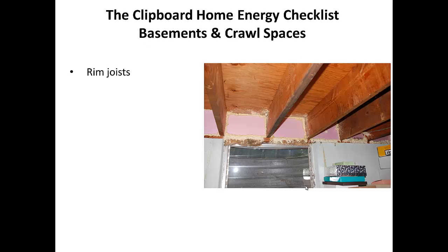So now let's go take a look at basements and crawl spaces. And here we're looking at a foundation wall and the first floor that's above it. And you can see what they've done here again with that Great Stuff foam. It looks like what they've done here is taken some blue board styrofoam and cut it fairly close to the opening dimensions, stuck it in there, and they don't have to do it a very perfect job because this foam is going to fill in any gaps that you would have. So this is a great way to reduce both air infiltration, which is the movement of air through cracks, and to stop those conduction losses, which is the movement of heat through a material, with this rigid insulation.